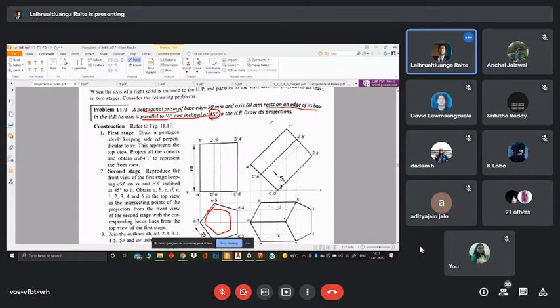As it is going to be tilted at 45 degrees, there is going to be one point where it is either closest to the HP or touching the HP. Our condition clearly states that it rests on the horizontal plane, meaning that it is touching the horizontal plane. So is it touching at a corner or at a side? It is telling us that it rests on an edge. Edge here means the side.